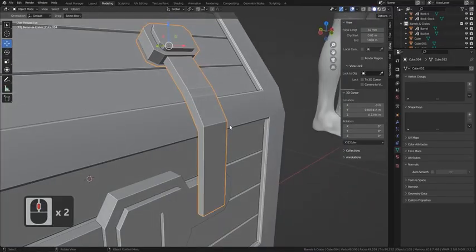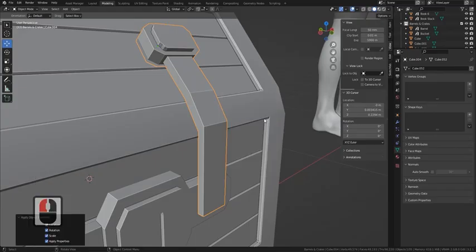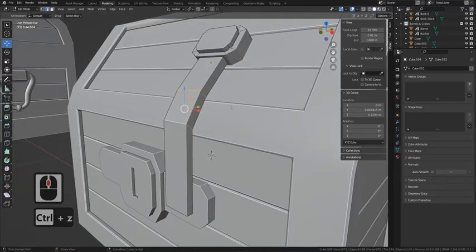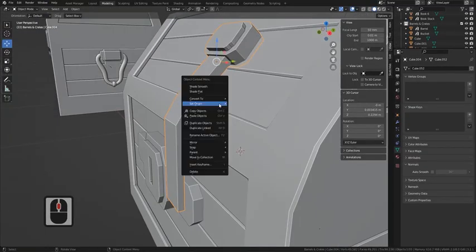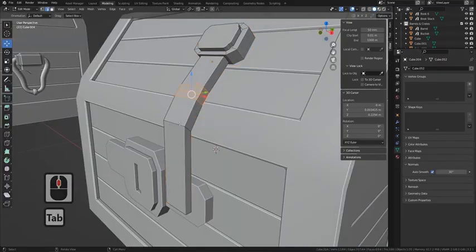And you can see it didn't really bevel that off very well. And of course, the reason is we didn't reset the transformation. So right click, origin to geometry. Now try beveling it off. And it should. Let's have a look. Let's bevel one of them off first. So Control B. There you go. That's looking better. Shade smooth. Let's bring on auto smooth. That one's looking nice. Now it's just this one.